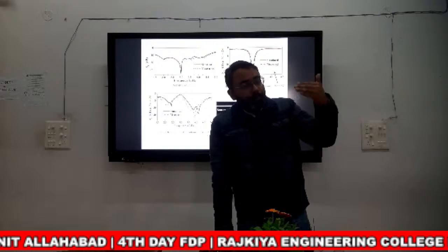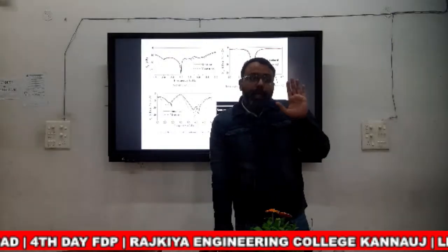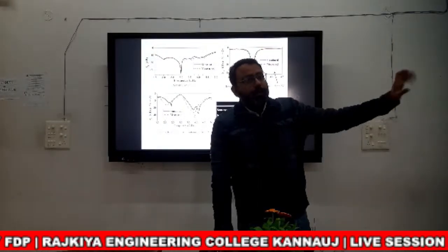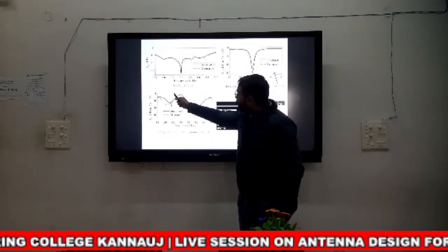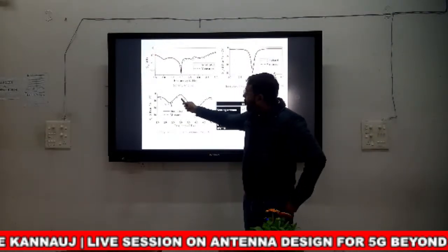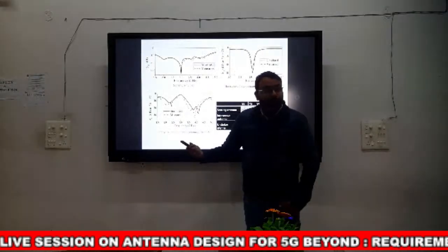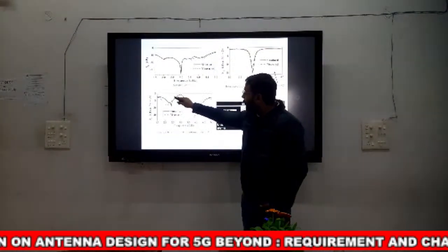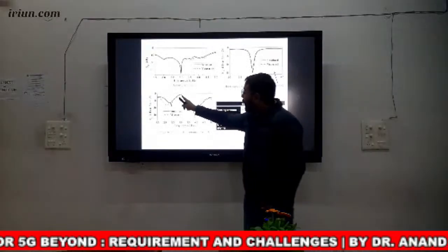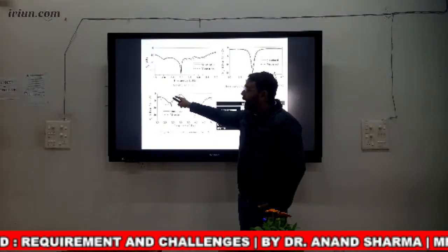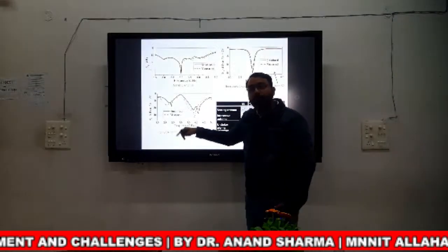If it starts the interference, then the secondary user goes away from the communication. So we have to create some band notching, because that part creates some interference. For that, what do we have to do? We have to do band notch. So we have created reconfigurability in this band notch with the help of the varactor diode.